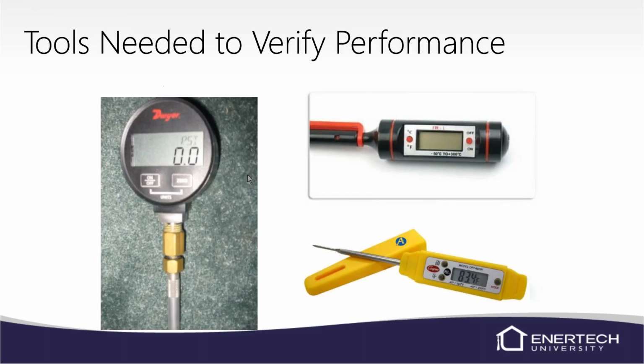So again, here's our Dwyer gauge. The one thing I want to say about this Dwyer gauge is sometimes we get into some really small units and we've got like a 1 pound pressure drop, sometimes even less than 1 pound. That's kind of hard to see on an analog dial type gauge. This digital pressure gauge is going to do the same thing, but it's real hard to see that little 1 pound pressure drop on a dial gauge. So that's why I do really like this gauge here.